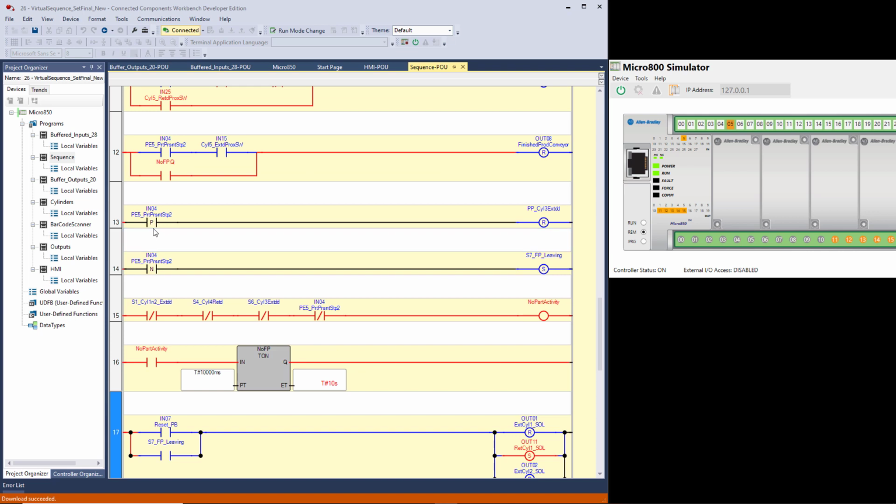I'm using a pulse rising true if on instruction to reset part present solenoid 3 extended, and I'm using when the pulse goes off to say that the part is left. So in other words, when this is part present solenoid 3 extended, that means there's a part sitting in front of the extended position for cylinder 3 on the finished product conveyor. If the part arrives at photo I5, that meant it left the other photo I, so we can turn that off.